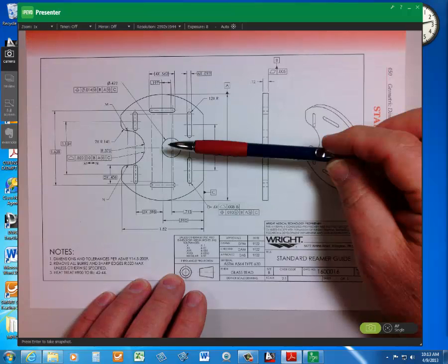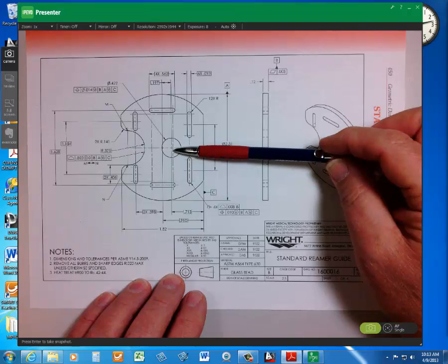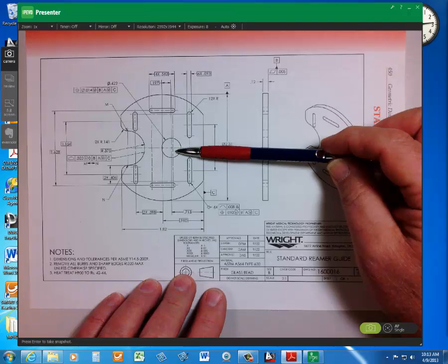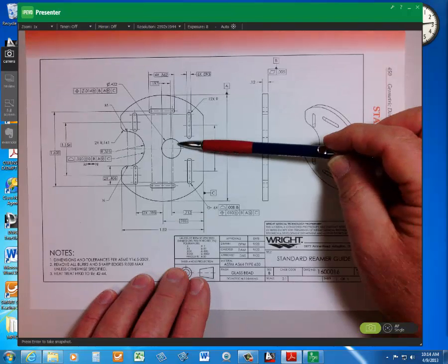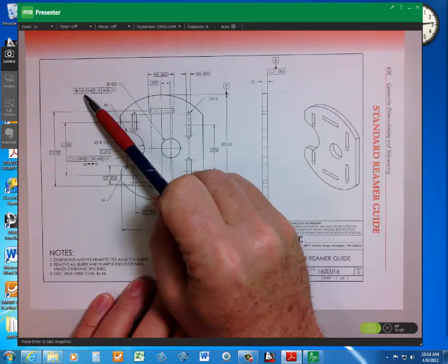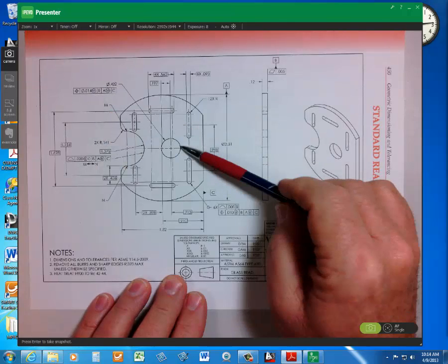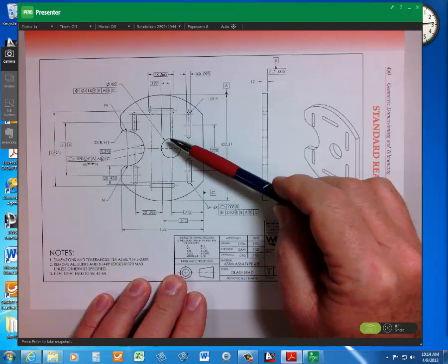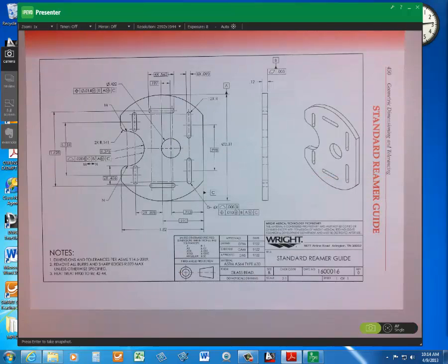And basically if that pin slides into the hole, and the pin is 0.403 diameter, it has achieved location. We know it's a good part. Over the full range of size and tolerance, its virtual condition is always going to be 0.403. So we know it'll fit over that 0.403 diameter rod that's on true position.